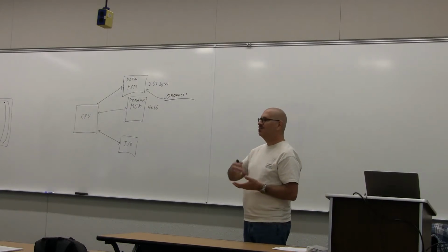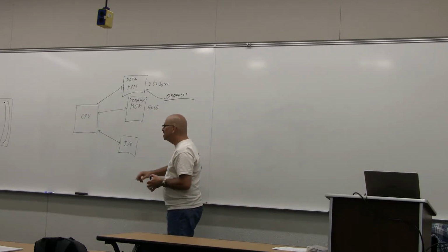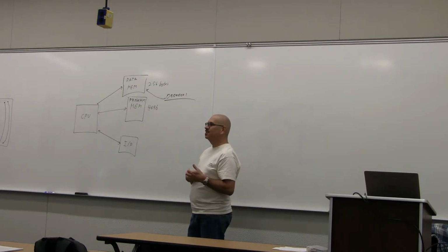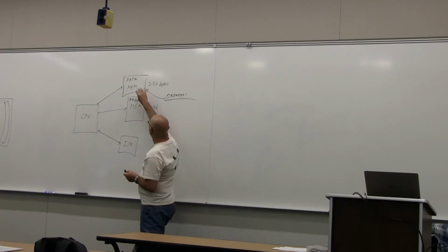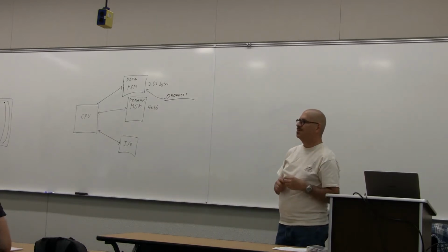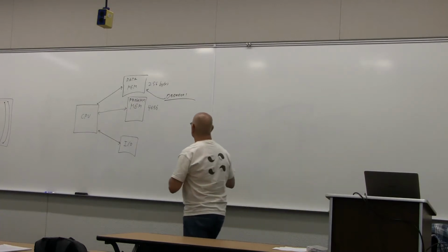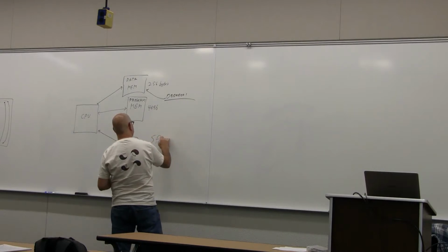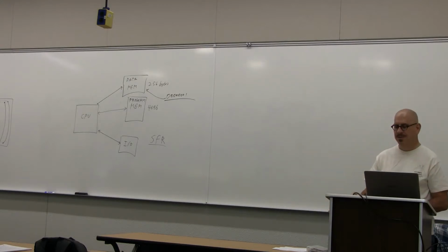And there's another location that if I write into, it starts to set up this timing subsystem. So we can generate events every 3 seconds if we want. And there's another section that if I read from, it's actually reading an analog voltage coming in and telling it how to convert that into a digital number. So there's this whole subsystem for doing input-output, but it acts like a data memory. It's just particular locations in our data memory don't actually correspond to general data. They're I/O functions. And so these are called special function registers, or SFRs. And we'll be doing a lot with SFRs in this course. It's how you get out of the box, basically.